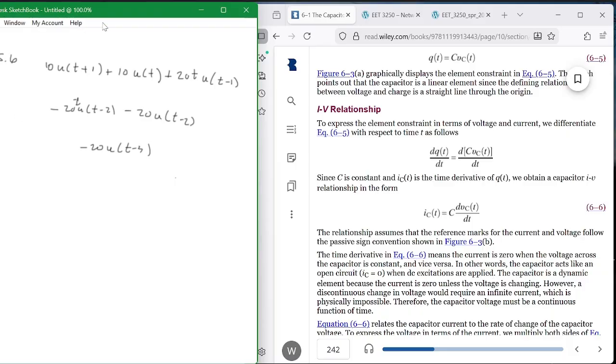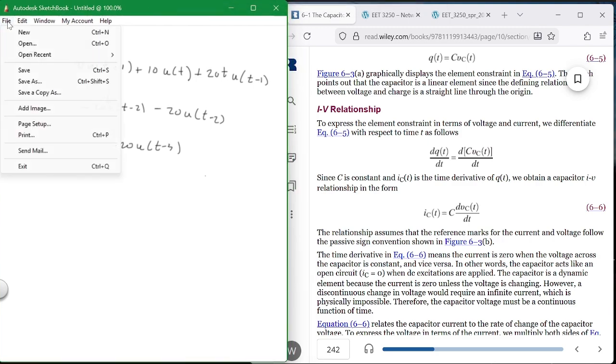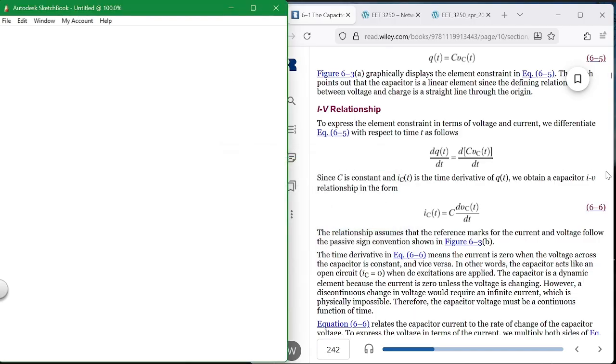If you remember me from other courses, I get into this ICE thing and ELI the ICEman, and I ask you to remember that. And here it is. It's I equals C dV over dt, commonly called ICE. Okay? And if you can't remember this, remember this, and then you can put the dV over dt over instead of E and you're in.